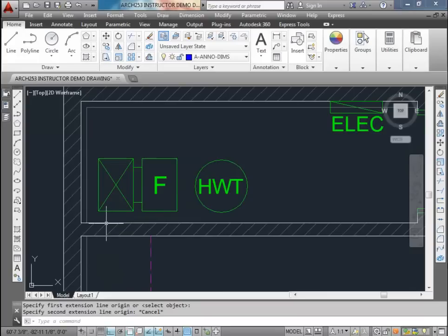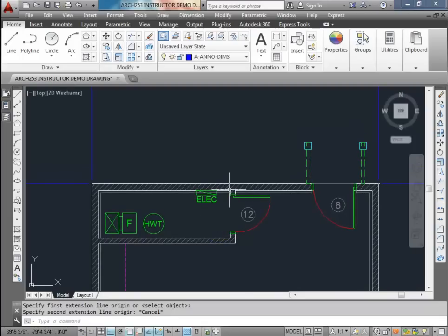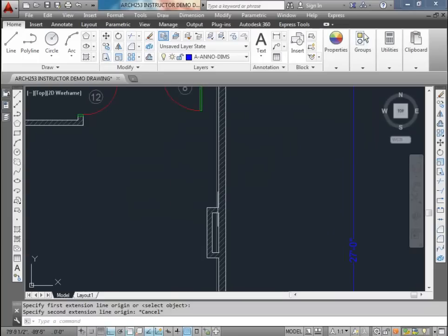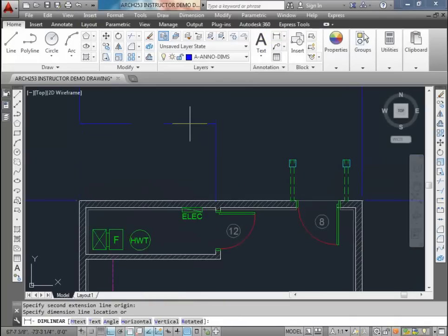If we choose either side of that wall, we have to be consistent with the side of the wall that we choose. So I can't switch it up. For example, this one I'll go to the left side, and then when I dimension this one, I'm going to go to the right side. I don't want to do that. I want to pick a side and stick to it. Okay, so in my case here, I'm going to go to the left side, just because I decide to go left today. It doesn't really matter as long as you're consistent.